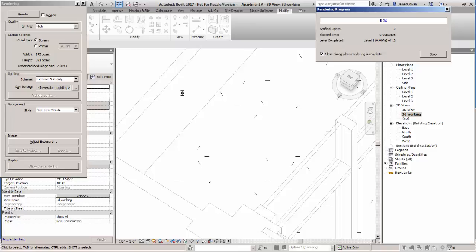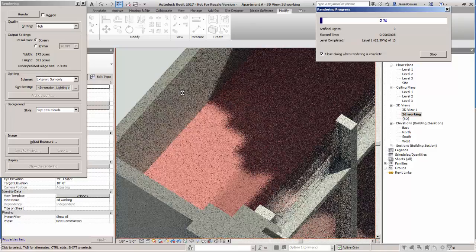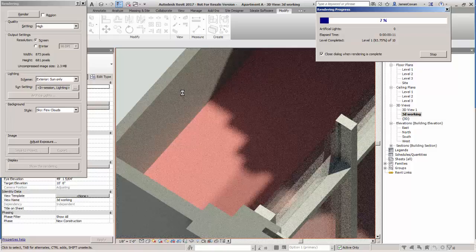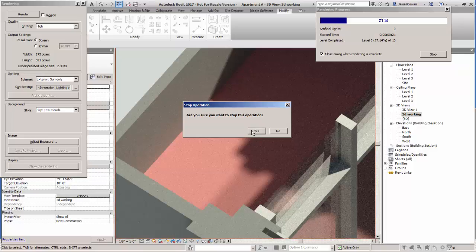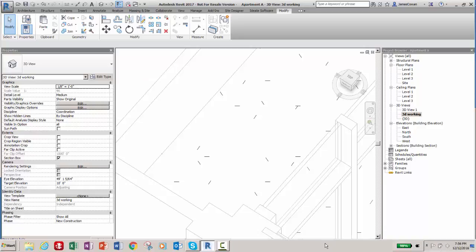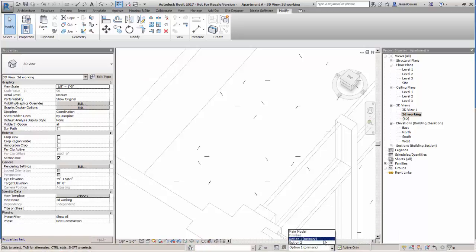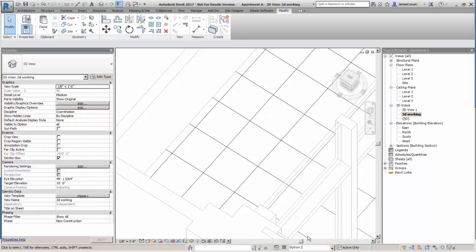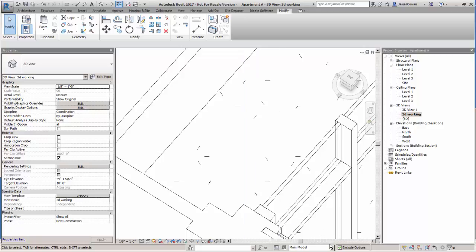So the last part in this was to show you that when you have design options, it's possible in Revit to check different options inside a project. But remember that if you blow away the design options, all views that contain them will be blown away as well. So the technique is usually to pick which option your client decides they want to keep. There's the one with my tile, there's the one with my concrete.